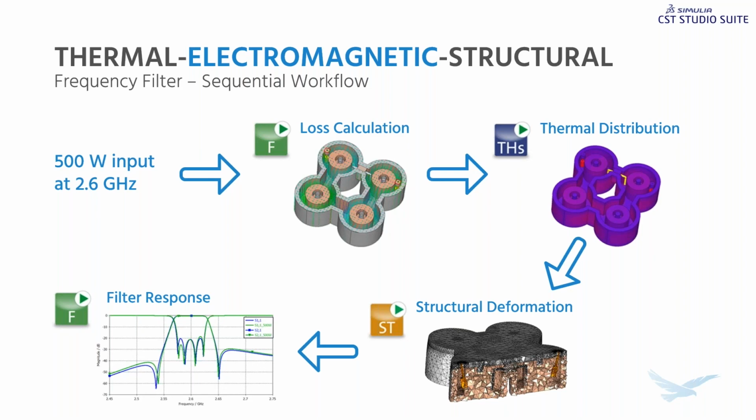Or we could start looking at doing some of the problem in flow simulation and moving to SolidWorks simulation. It does depend a little bit on the interactions, and I probably need to know a little more about the problem, but on the surface, I'm expecting that the deformation is happening and changing the electrical path through the part, and so the Abaqus workflow is probably going to be the best. Right. So in Abaqus, the thermal and structural co-simulate. Exactly.